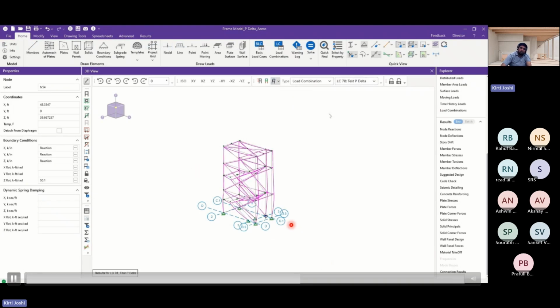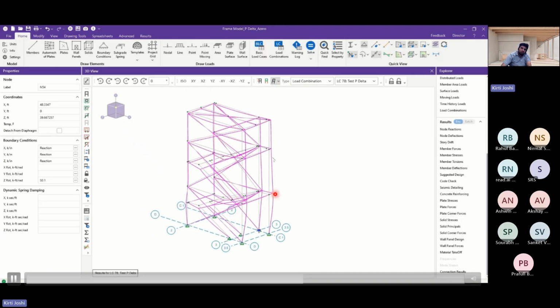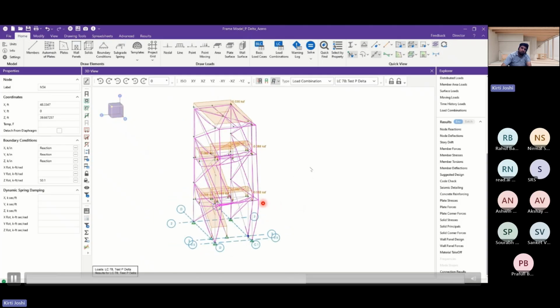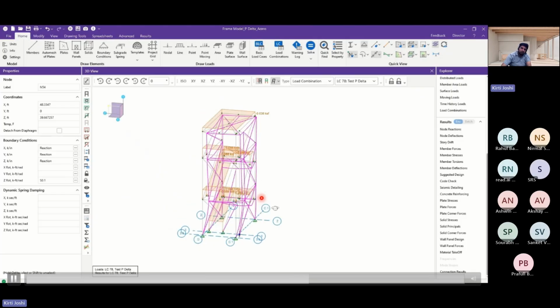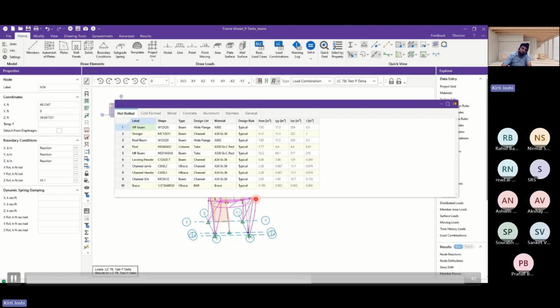Now I can see the deflected shape again. Right now, the issue seems to be because of flexibility. Even under these loads, where this model has only vertical loads, not even the gravity or the lateral load, the columns are not stiff enough. The model is too flexible.